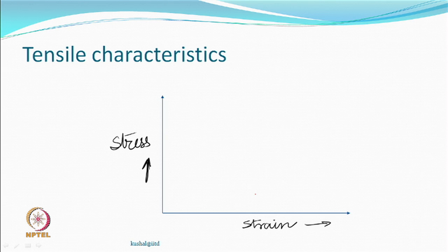So, we would like to measure the tensile characteristics also, like a stress strain curve. So, we said this is a bulk yarn. It may give a curve like this. What you can measure is the stress at break, elongation at break, and modulus, generally expressed at 2%, otherwise 2% extension.